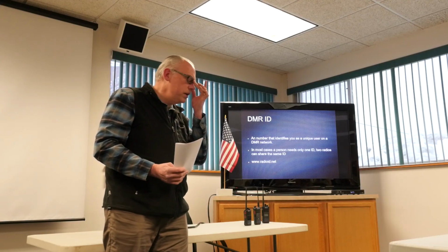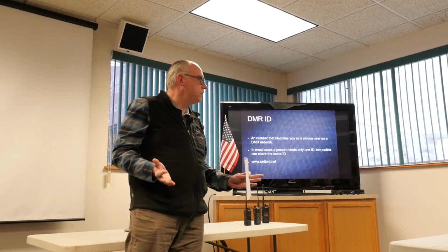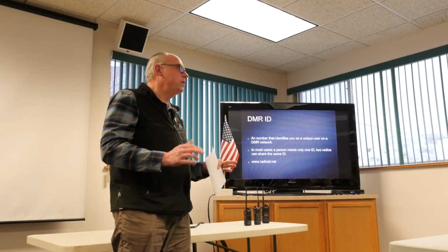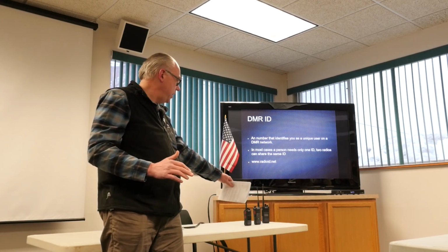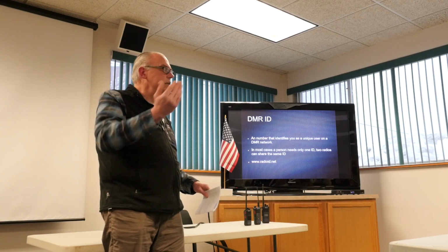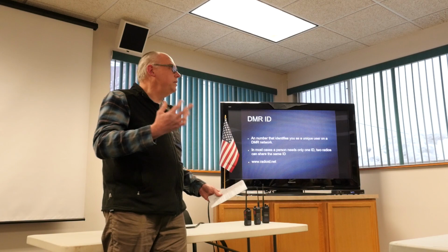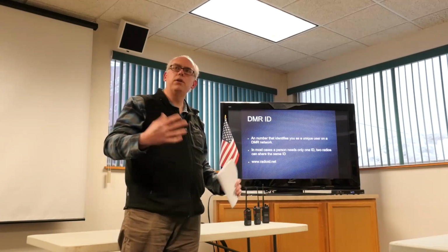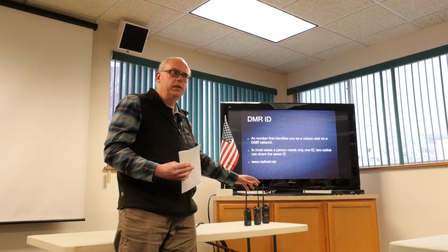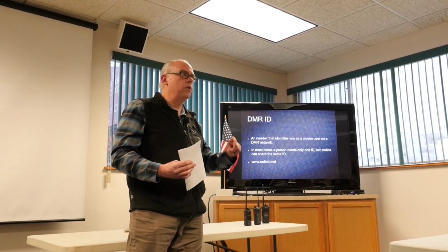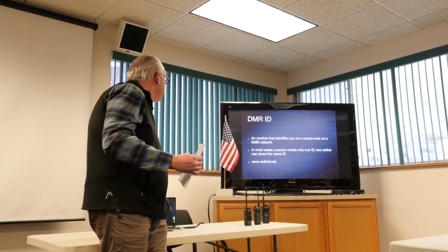Now the thing to consider though is your DMR ID is not your method of identification for purposes of the FCC. So even if you've got your radio programmed so that when you transmit, your ID number shows up on the radio, and potentially your call sign on the radio that's receiving your signal, you still need to identify with your call sign over the voice channel, because your call sign is not being transmitted on the DMR data stream, only your DMR ID number. So that makes sense? Yeah. Okay. Talk groups.